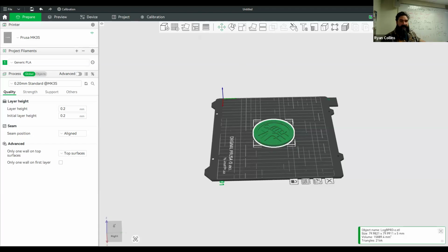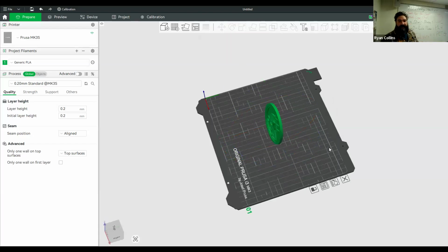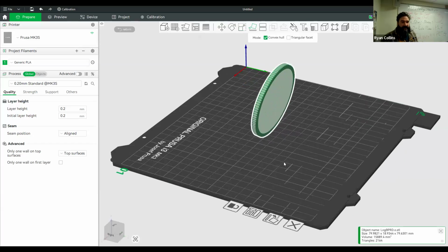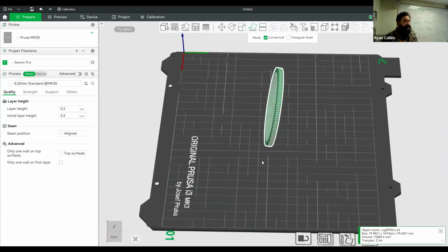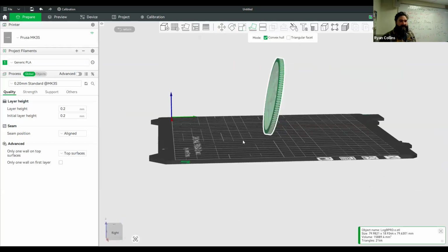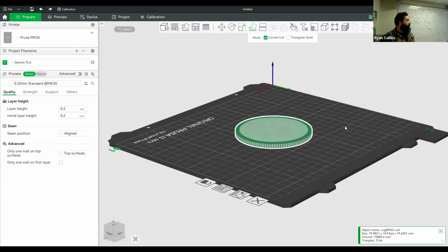If it doesn't put it flat down like that, the other one is the same symbol, but without the auto version. It's called place on face, lay on face. Once you select that, now you can see that it's highlighted the major faces of the object. And this makes it really easy to orient a large flat object right on there. So what you want to make sure to select is the back side, the side without your logo. And it's going to snap it right down.